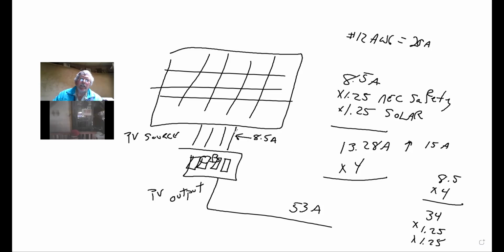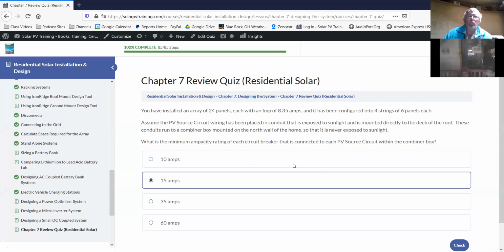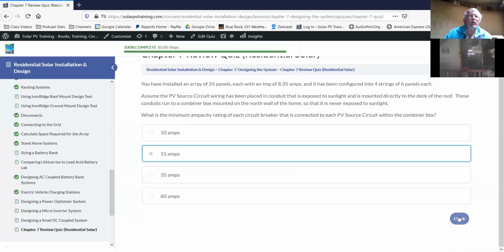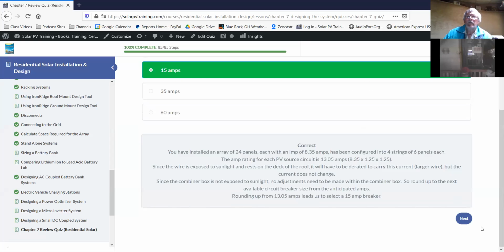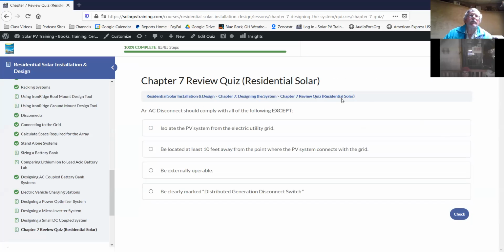The temperature adjustment is dealing with the fact that the wires are not capable of carrying as many amps as they were rated for. So you need to put a bigger wire in, but you're not increasing the number of amps flowing through that wire. So that's the subtle distinction that you gotta sort of begin to understand. When you're making temperature adjustments, you're simply adjusting for the ampacity characteristics of the wire, not the number of amps that are flowing through that wire. Hopefully that makes sense to everyone.